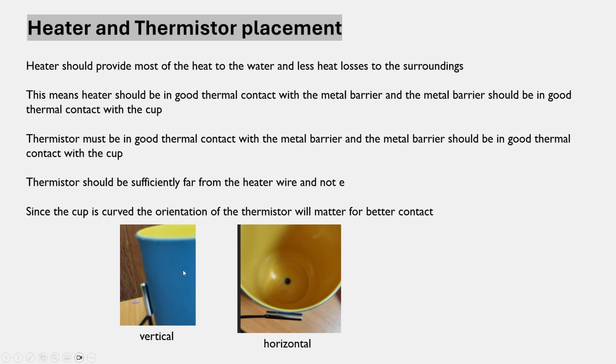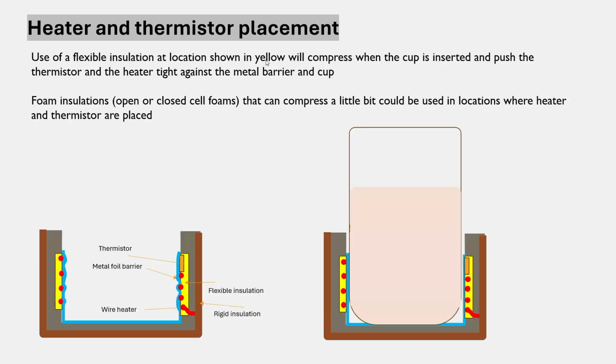So it's up to you, but ensure good contact. Another aspect of placing the heater and thermistor is to ensure that it's always pressed up tight against the cup warmer. One way to do that would be having some kind of elastic material or some kind of spring that will compress when the cup is in place and push up against the surface.